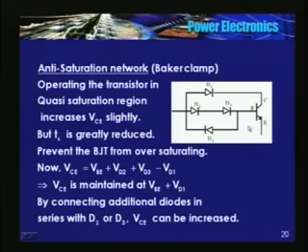Assuming that all the diodes have the same voltage drop when they are conducting, VCE is maintained at VBE plus VD1, the voltage drop across one diode. Now by connecting more diodes in this part, you can increase VCE. I have just connected 2.